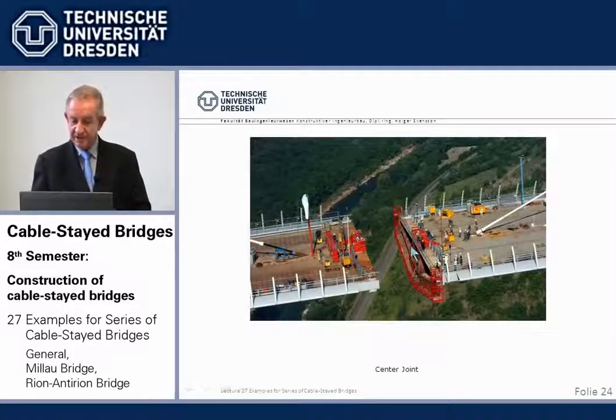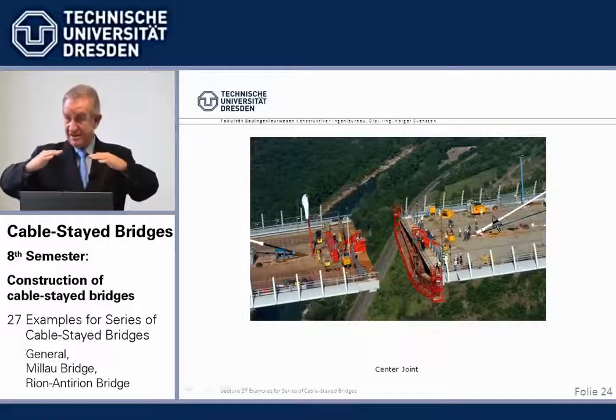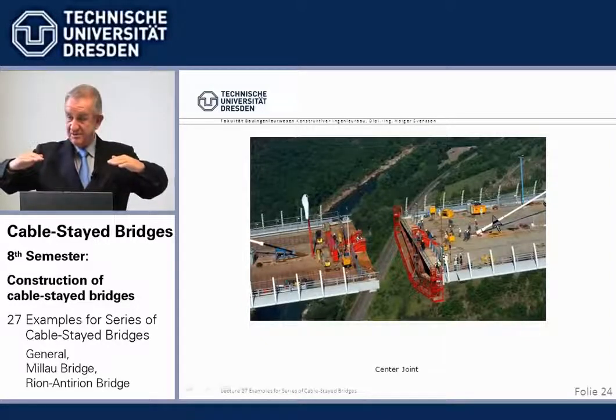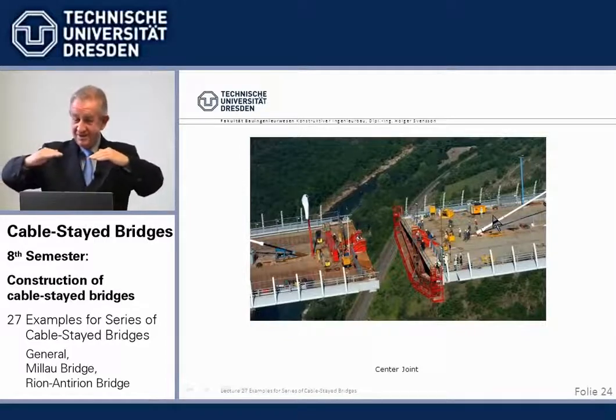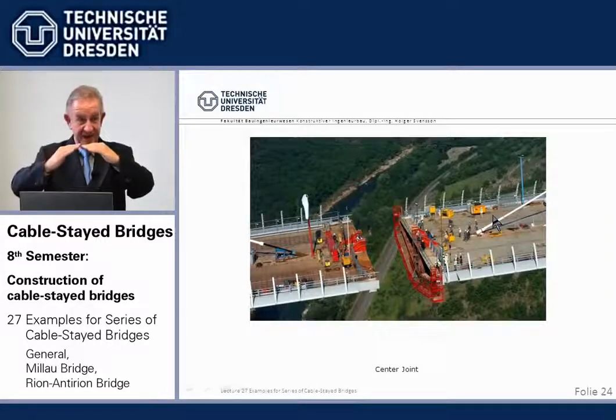We come then to the closure joint, to adjust very carefully. Of course, it helps here immensely to be able, in this case, to pull at the cables. You know, normally, with cantilevers of 170 meters each side, you do not come exactly; you need to be in level, and you have to have the right angle.